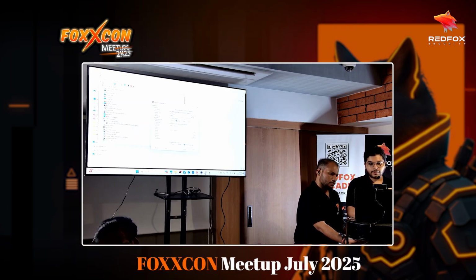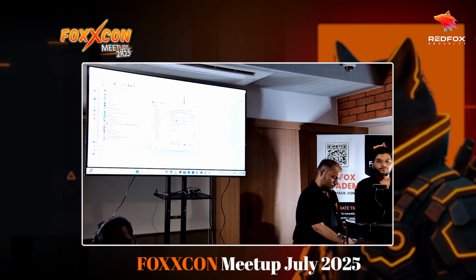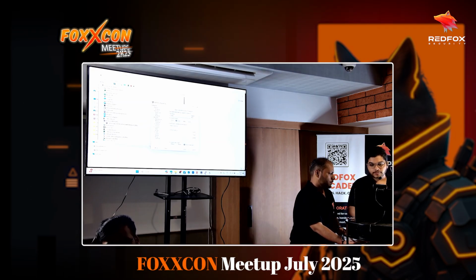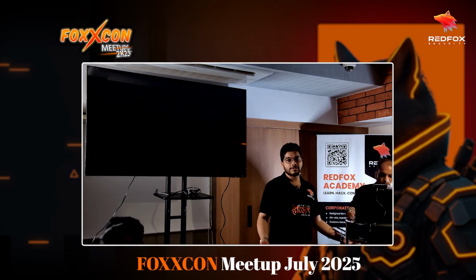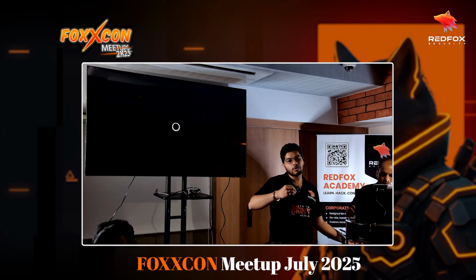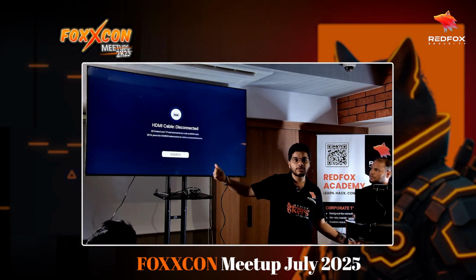And one more thing that I missed out when I was explaining UART is that the pace of information transferred from the device to our computer could be different. It could have a lot of variations. There are lots of defaults, and the one mentioned here is 9600. Speeds for devices transmitting from, let's say, a router to your computer could be a lot of different things. UART specifically runs on a lot of different default speeds, and it is an asynchronous protocol, as was mentioned here.